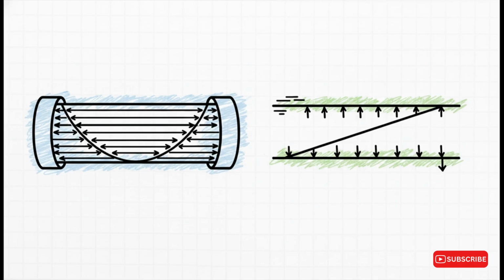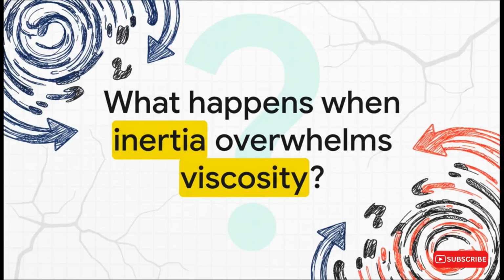For instance, in a circular pipe, the fluid forms a perfect velocity parabola. The dead center moves the absolute fastest because it's avoiding the drag of the walls. Or, if fluid gets trapped between a stationary bottom plate and a moving top plate, you get this pure, straight-line shear profile. Momentum is just handed down layer by layer with zero pressure driving it. It's actually really elegant.